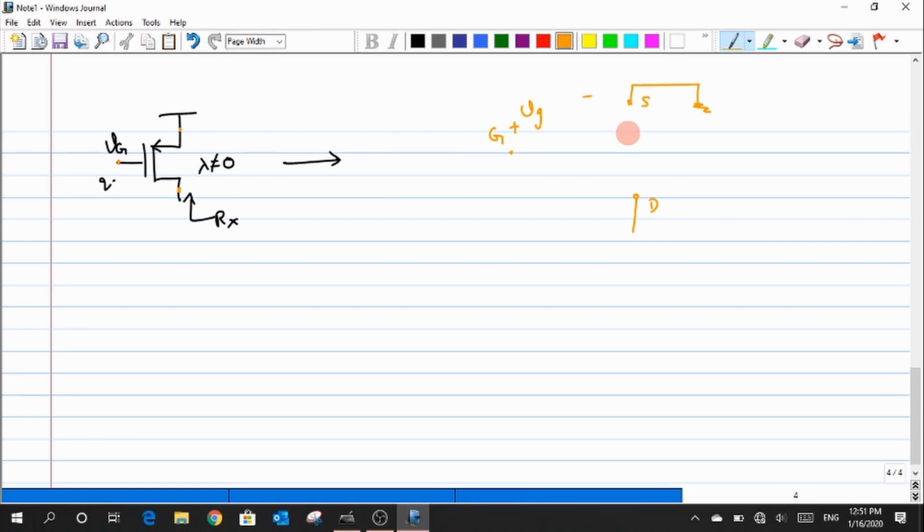No. In the last class what I said is that for the small signal model there is no difference between a PMOS and NMOS. It is the same. Only when it comes to DC we have to think about whether it's a PMOS or NMOS. So in this case it doesn't matter. It only depends on the polarity of my VGS, nothing else. The source is the least potential, due to which the current flows towards the lowest potential in my circuit. So I draw something like this, and it is written as Gm times Vg. And what is left over is just the R0. That also I fix.